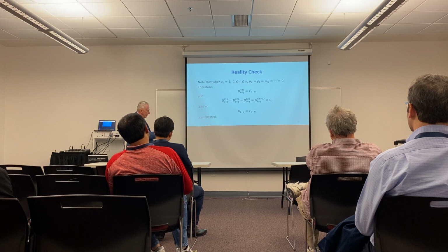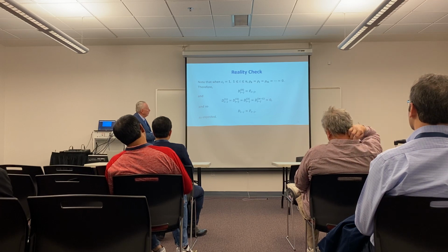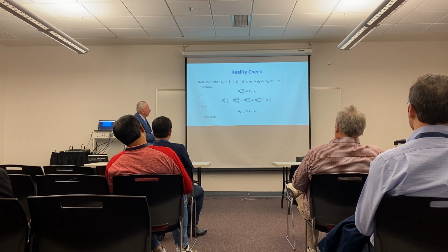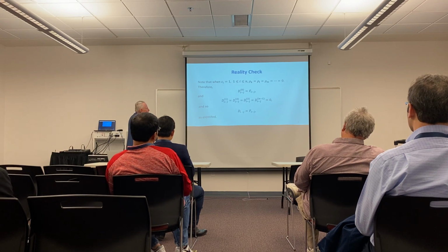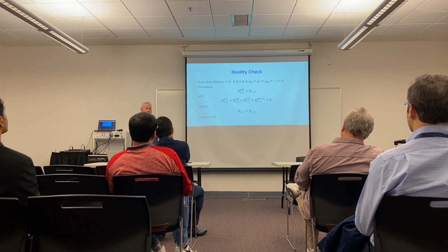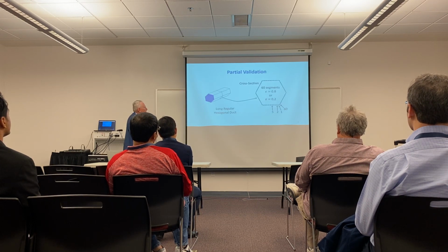So the 0th order term here is just equal to the geometrical factor, and the other orders are all equal to 0 because they have reflectivities in them, which are all equal to 0. So you end up getting Dij equals Fij, which is of course true. We know that to be true, so we passed one hurdle here in our logic.